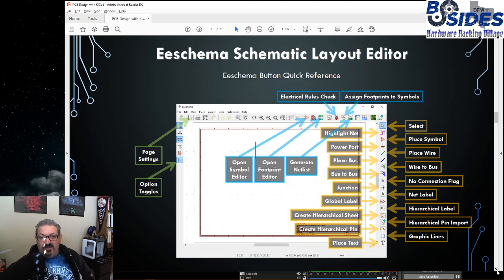So let's take a look at the Schematic Layout Editor. There's a couple things of note. Your page settings is one of the things you should probably set right away, because changing it later could move things around on the page where you don't want them. This is where you'll set the actual dimensions of the page, both for a screen view and for the paper layout, whether you're using A4 paper or US letter sized paper when you're printing to paper or to PDF.